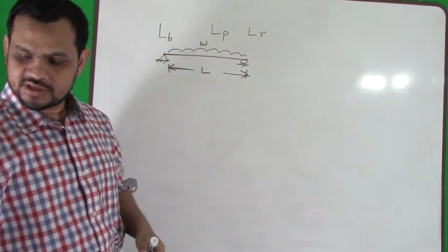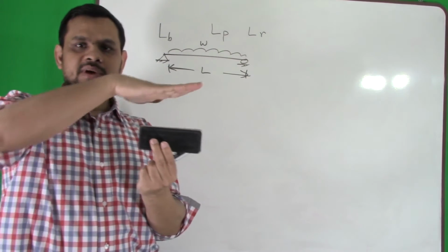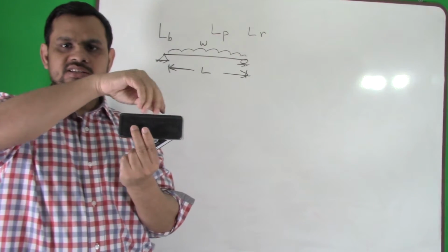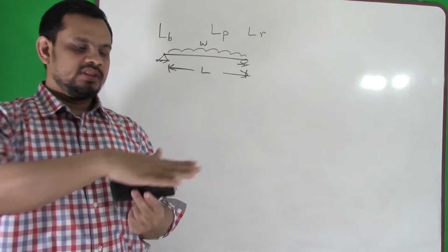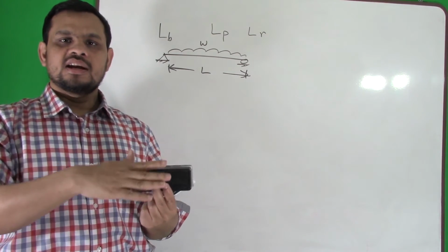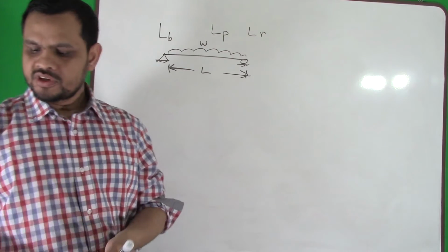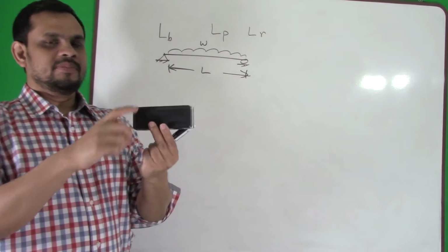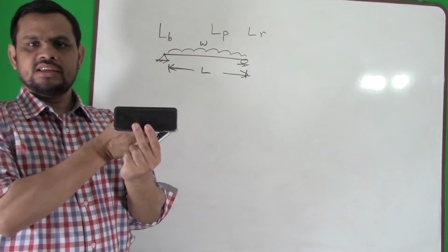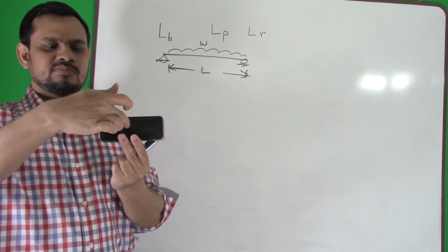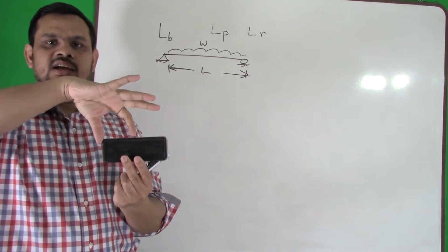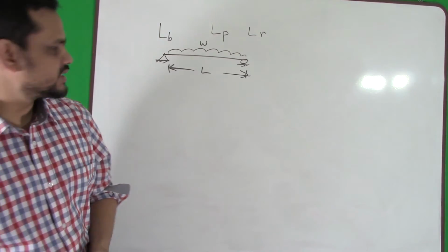Say my beam is here, and if I have a slab on top of this, attached to this beam, then the beam cannot move. So in that case, we can call laterally unsupported length is 0. So this way, if I provide a support at the middle here, that means this beam is laterally supported at this midpoint. That is my LB. So we will see that.